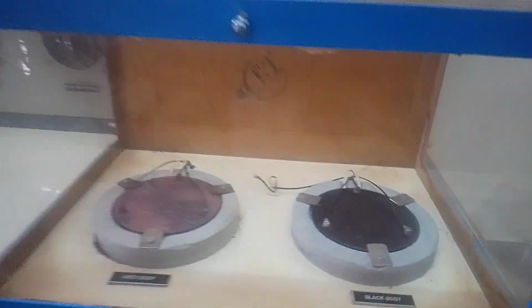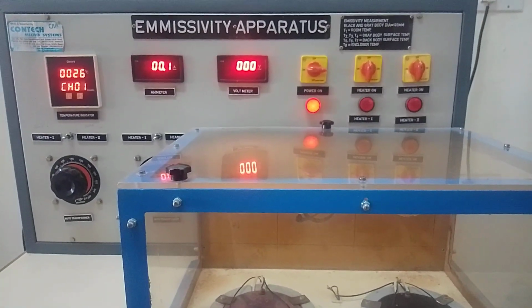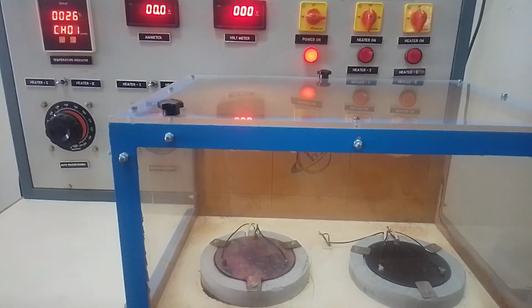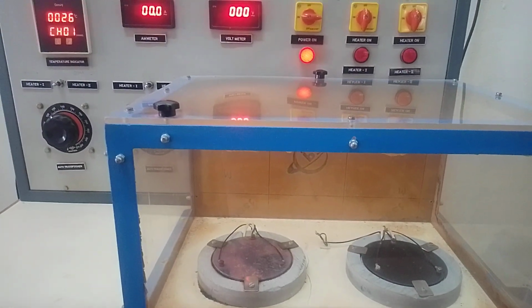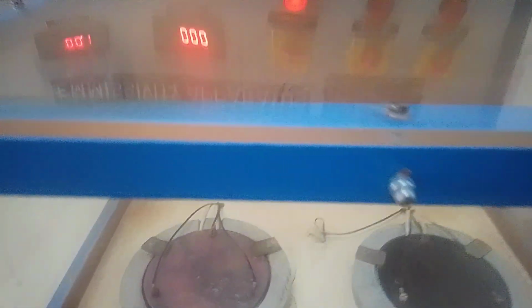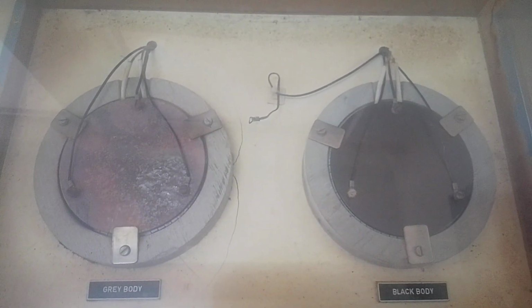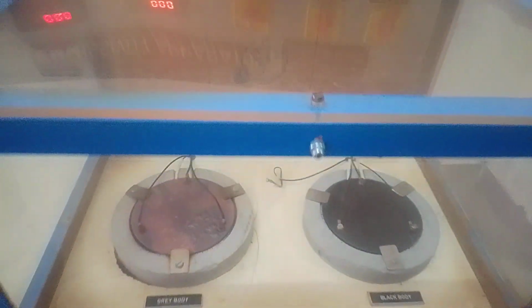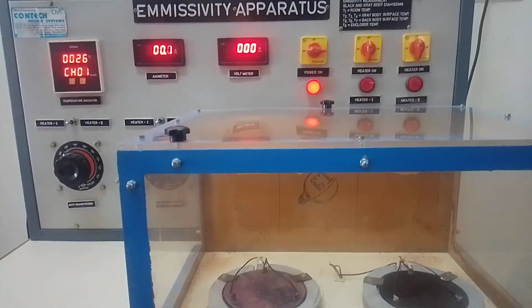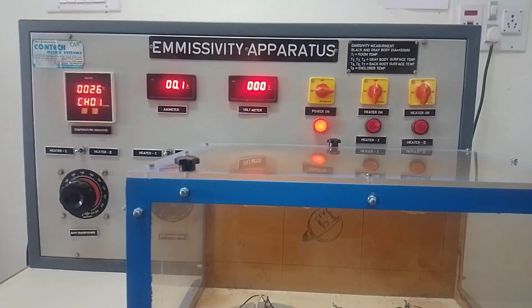Emissivity of a surface is defined as the ratio of the radiation emitted by the test surface to that of the black body surface at a given temperature, and is a measure of how closely a test surface approximates a black body. A black body is an ideal surface which absorbs and emits the entire radiation incident on it. However, other surfaces like polished or glassy ones may not emit radiation as much as a black body. Emissivity lies between 0 and 1 for the grey body surface. The emissivity of the grey surface is not constant; it varies with temperature, wavelength and direction of emitted radiation.